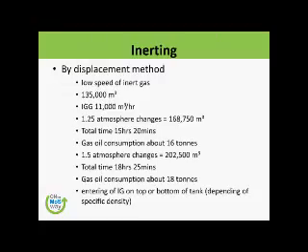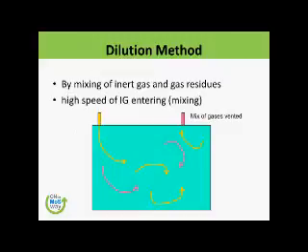Okay, let's press on. This is a dilution method. What we are doing in the dilution method is mixing inert gas and gas residues. If we throw the inert gas very fast into the tank, it will create eddies, it will create turbulence, and of course the mixed gases will be vented out. But the problem here is that you need a significant amount of inert gas to replace or change the environment to safe mode.